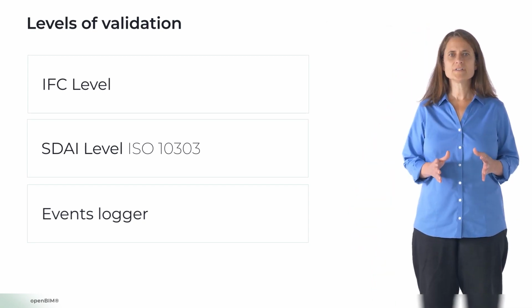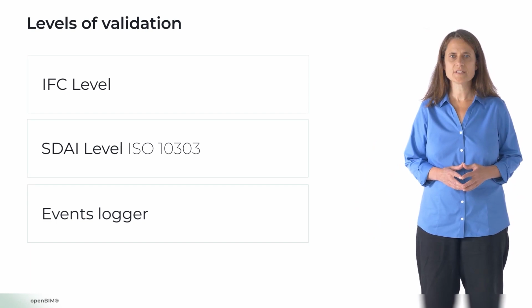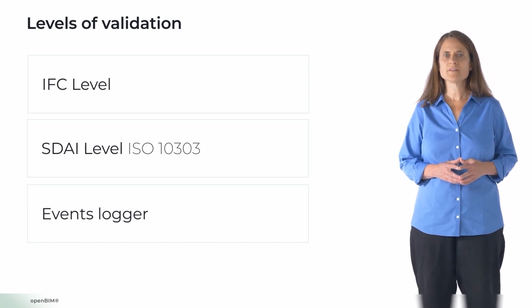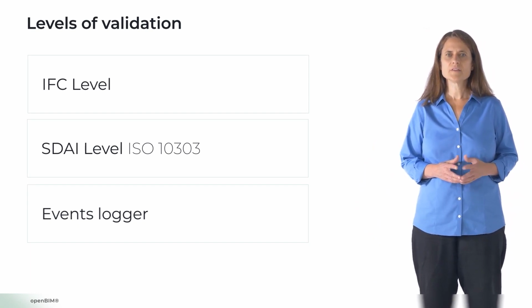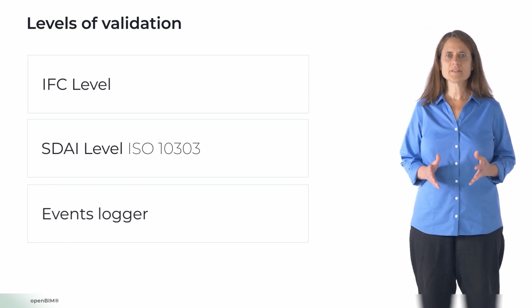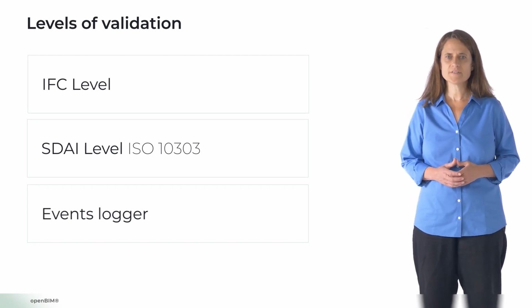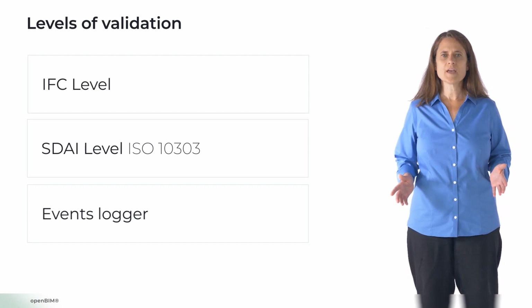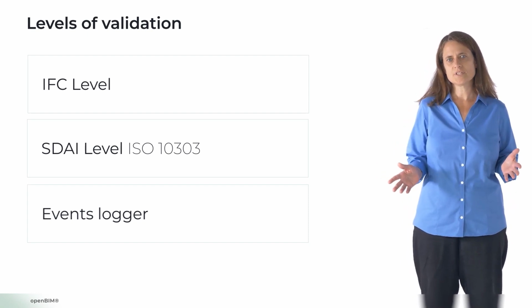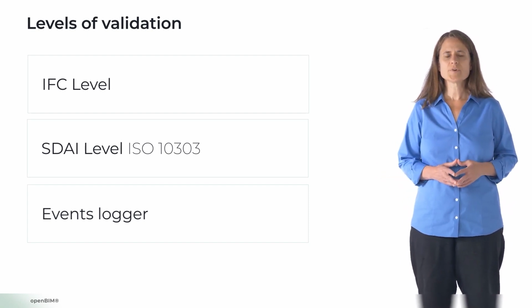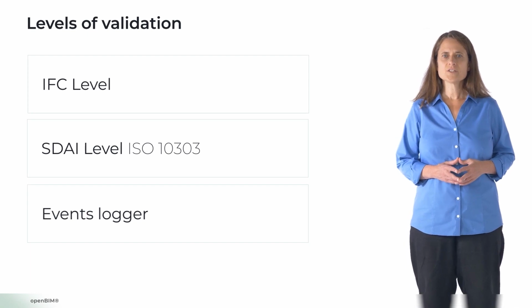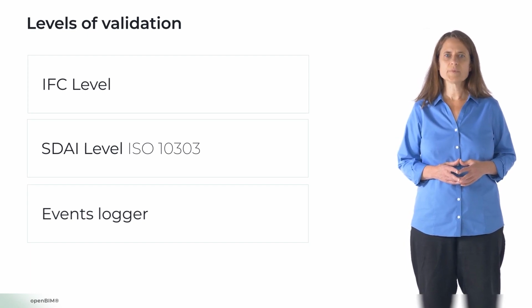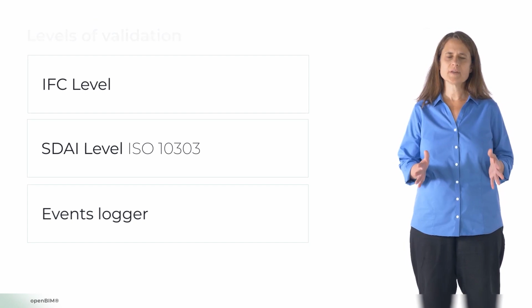And the highest level of validation available in IFC SDK is format-dependent verifications. These include implemented collections of validations on the IFC level, forthcoming MVD, model view definition validation, which is in progress now, and validation according to the new IDS requirements, which are currently being developed by BSI.